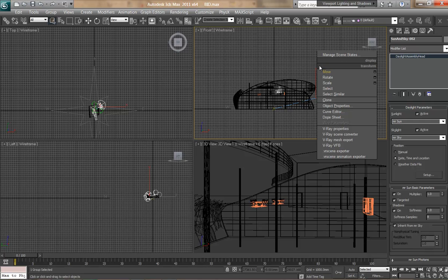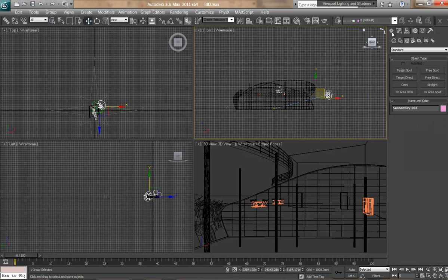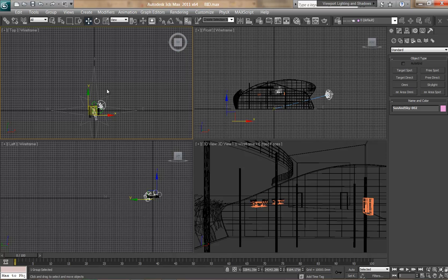Now, if you bring it in from another program, like AutoCAD or ArchiCAD, any other CAD program, SketchUp even, there's nothing wrong with making your own daylight system in 3D Studio Max, and you can do that here. It's not under lights. It is basically a light, but it's a bit more complex than a normal light. So it's grouped under Systems, which is the last of these options you have on the main Create panel, and so you can make a daylight system there.